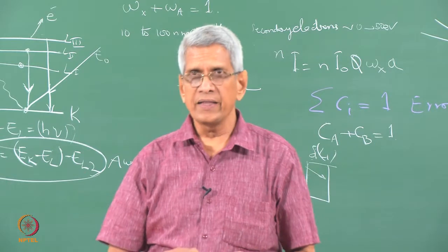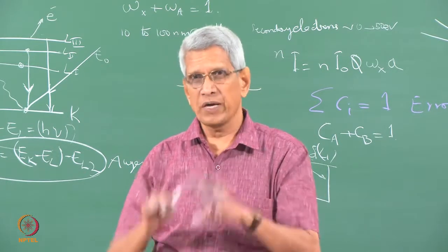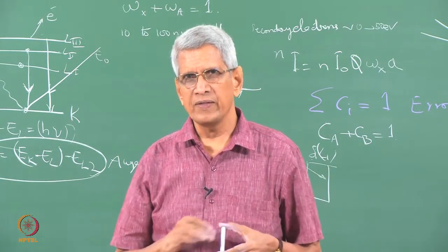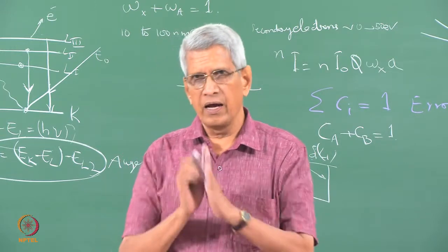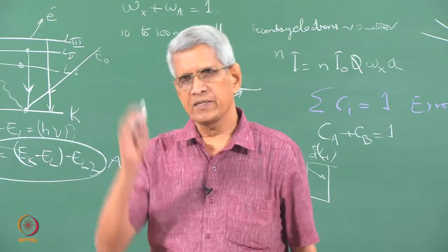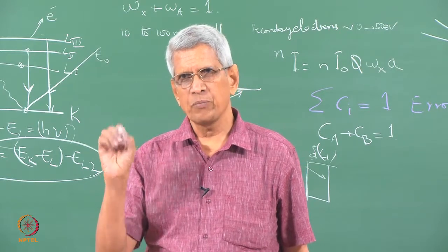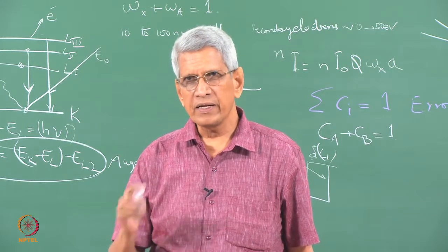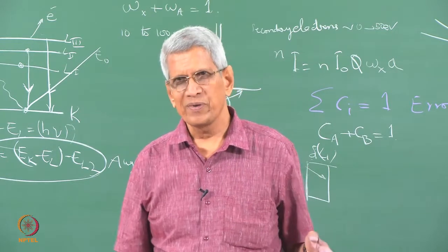Another is, normally you see that earlier people used to give X-ray mapping, how the distribution of the various elements is done. There, what is being done is that you put a window, choose a window corresponding to a specific element. When the next signal comes corresponding to that, it is marked at that specific position as a dot, a bright dot. But whether that dot is coming from a Bremsstrahlung or a background, we do not know.